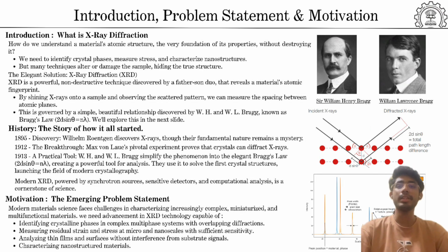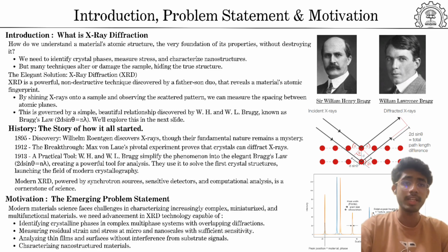Introduction. To understand materials' atomic structure, we need to identify crystal phases, measure stress, and characterize nanostructure, but many techniques alter or damage the sample. The elegant solution is X-ray diffraction. XRD is a powerful and completely non-destructive technique that helps us understand the atomic structure of materials. By shining X-rays on the sample and observing the scattered pattern, we can measure the spacing between the atomic planes.